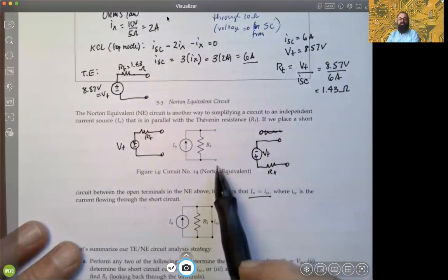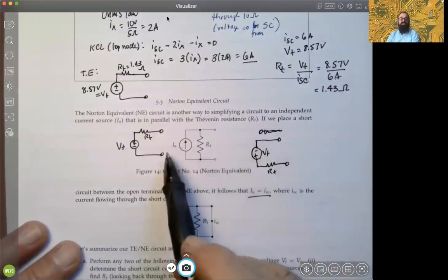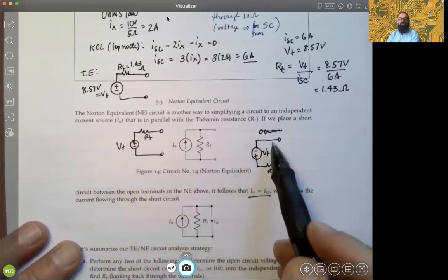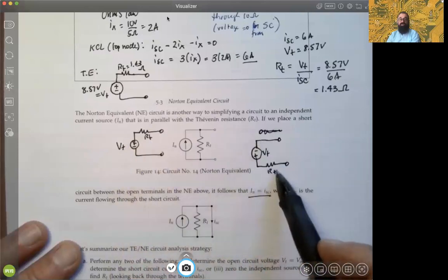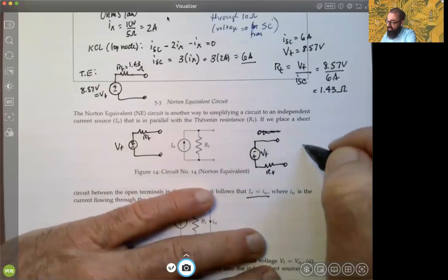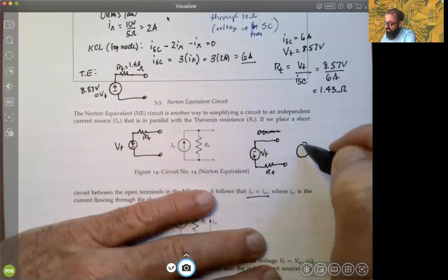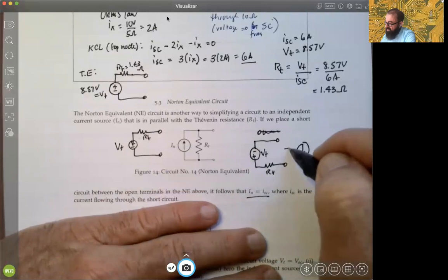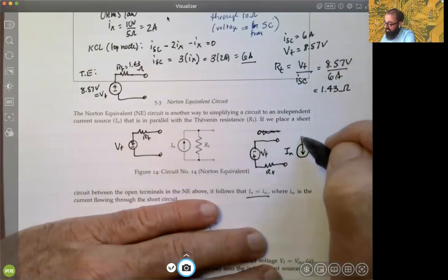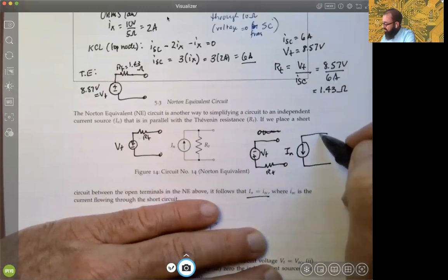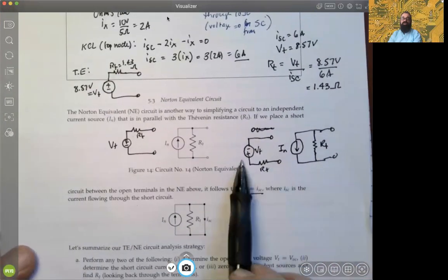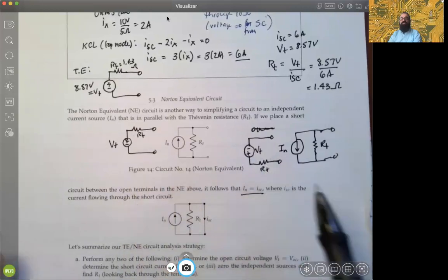So this is different, right? Because now the current is flowing upward. So that energy is released and absorbed. Now the current is flowing downward, release the energy, absorb, okay? So if you wanted the Norton equivalent to this, you could find the IN value, because IN is the same as ISC from the Thévenin, excuse me. But now you must draw the arrow down. The good thing about parallel is you can't get that wrong. There's no right or wrong on the up and down there, but it's in parallel. So notice the difference here. They need to stay in alignment, okay?